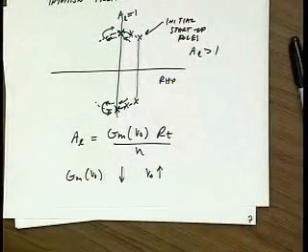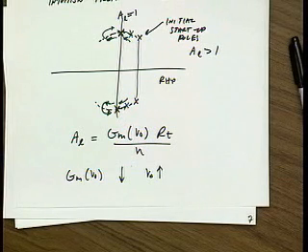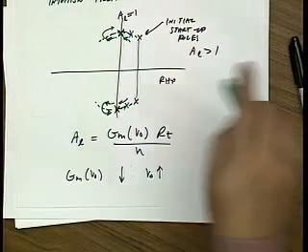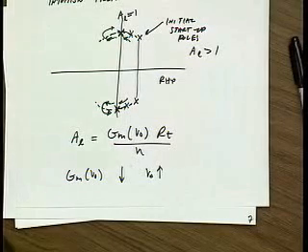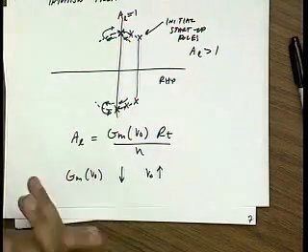Okay, Caleb? So can the setup you showed us ever be unstable? Can the oscillator be unstable? The setup you showed us, the inductor feedback. Yeah. In fact, somebody asked me last lecture, what happens if you have too much loop gain, for instance? You can get into a situation where the amplitude just keeps growing and growing, and the system just rails out, and then just dies on you. It's either supply rail. So you have to be careful when you design these systems that you simulate them over process and temperature, and make sure that your initial loop gain is a good choice that always leads to oscillation.